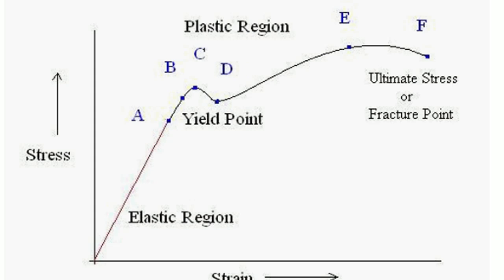So what is the yield point? That is the point where the material loses its elasticity and it will not return to its initial state when the load is removed. So this point C is called the upper yield point and D is called the lower yield point. We are always calculating this upper yield point when we are designing in the elastic limit.